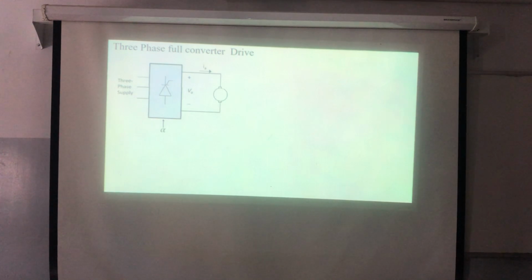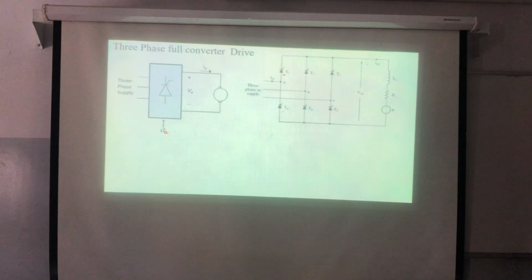And I need a firing angle here, so this one, if connected to the armature, will be alpha A. So here I'm having T1. If the current will flow via IA, the only possible scenario is to go through the positive T1 and the negative T4. IB, the positive direction via T3 and the negative direction via T6, and the same thing for the RC.